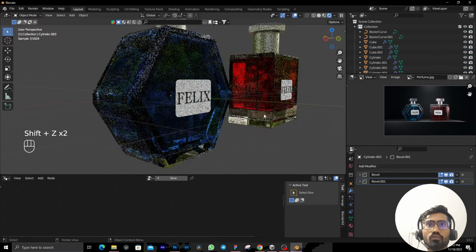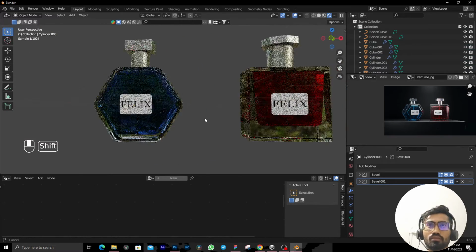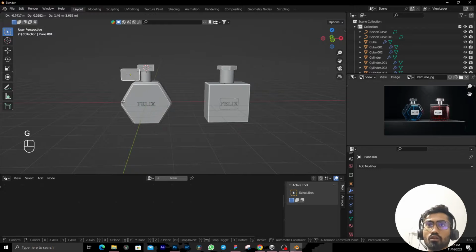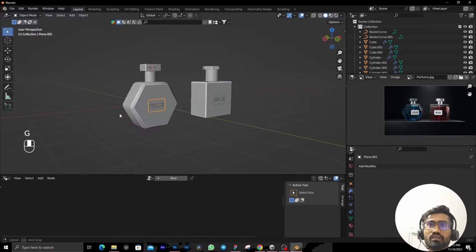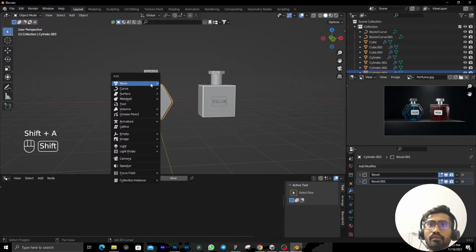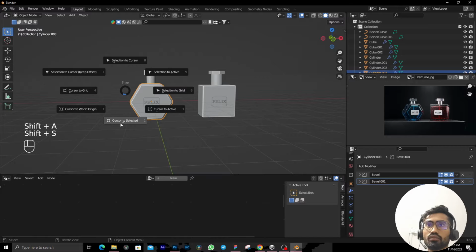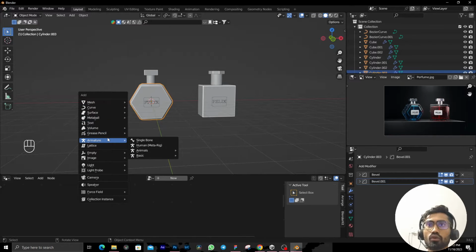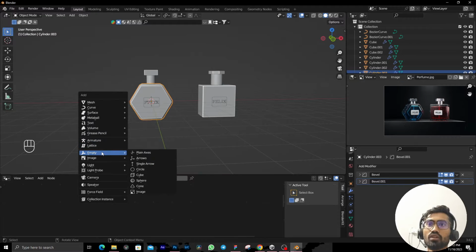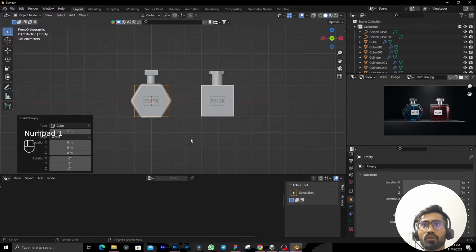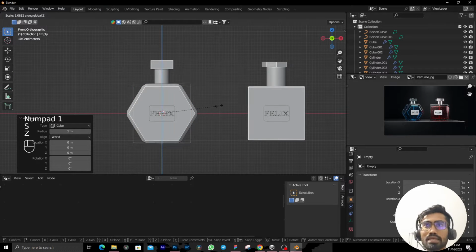And in order to move all of these objects together, you can do one thing. Right now all the objects are separate, you can't move them together. So you can add, go to cursor to world origin, add empty in order to control all of your portals. So for that, I'm just going to use a cube empty. Okay, going to scale it a bit.